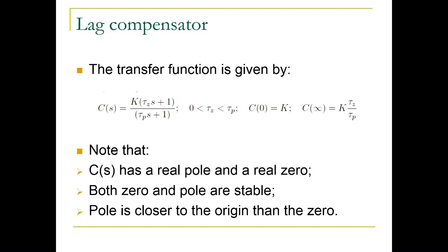There will be some parameters that you can tune, right? So each compensator will have several parameters that you can tune. We saw a similar situation in PID controllers. You had proportional, integral, and derivative action that you could tune, right? And tuning of these PID controllers was not easy. We saw, okay, Ziegler-Nichols give you some initial tuning rules, but we did not have a systematic way to choose these parameters. Now, what we will present now will give you a systematic way of tuning PID controllers.